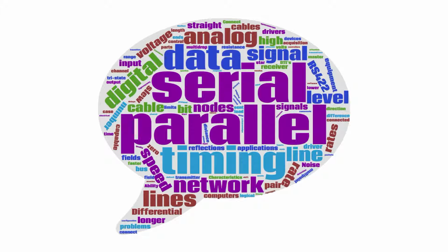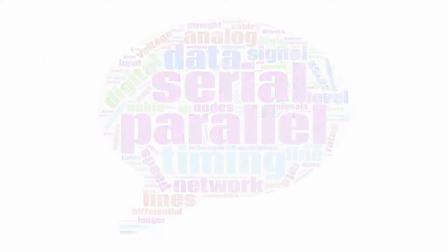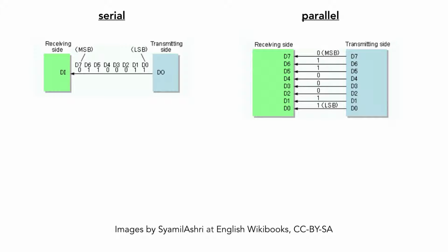One of the first decisions when designing an interface is, do we want to build a serial or a parallel interface? For serial communication, you break up the data you want to transmit into individual bits and transport the bits sequentially through a single connection. That's usually done with the help of a specialized chip, usually called a UART, for Universal Asynchronous Receiver Transmitter, although many UARTs also support synchronous communication depending on the protocol implemented.